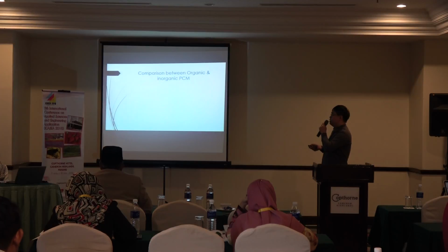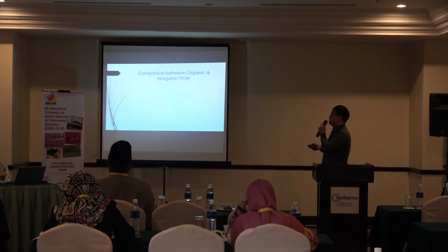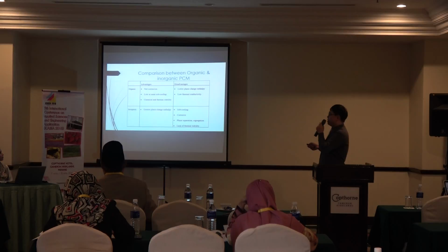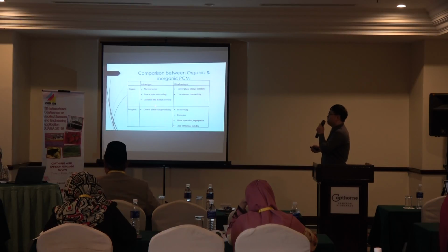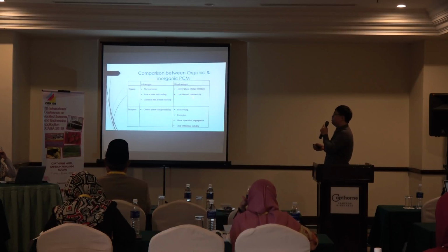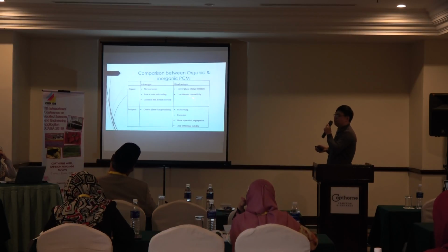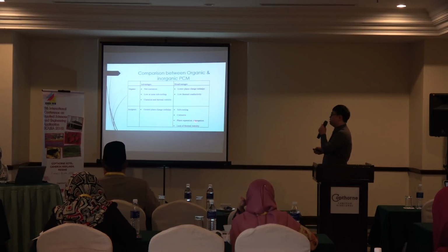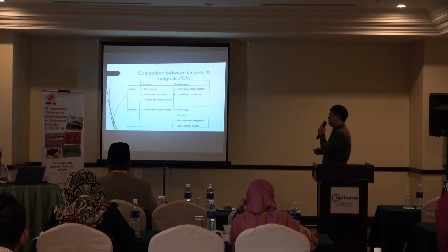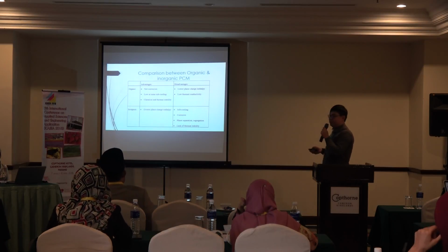So next, I will give some advantages and disadvantages of the organic and inorganic phase change materials. Organic phase change materials are non-corrosive, have low or no subcooling, and are chemically and thermally stable. However, they face lower phase change enthalpy and lower thermal conductivity. However, the inorganic phase change materials possess great phase change enthalpy, but they suffer from subcooling, corrosiveness, phase segregation, and a lack of thermal stability.